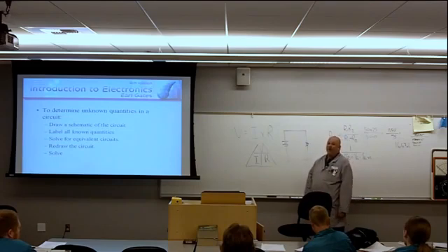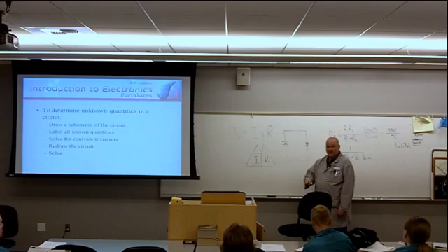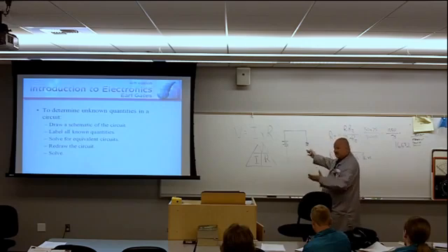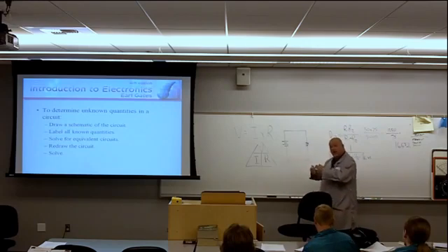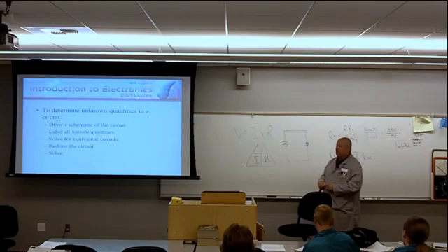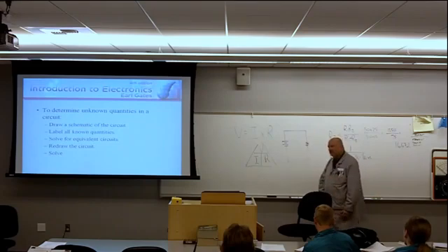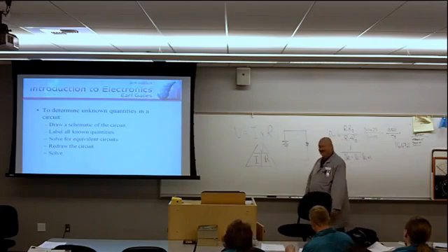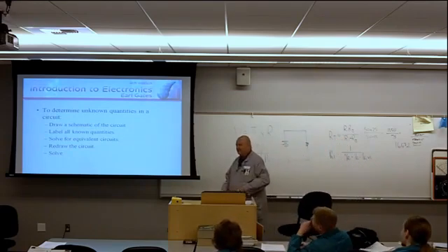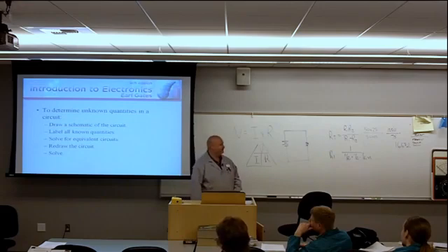And I'll tell you what, if you go out to your car and you turn the key and there's nothing, and you open the door and the dome light doesn't come on, nothing works in the car, all of a sudden this is exactly what you've got, and there's an open in this circuit, and it's a pretty big open, or your battery's dead. I don't think your whole load is dead. It's not like, oh my goodness, I've got to replace the load but save the battery. It doesn't work like that. But do you see the power of troubleshooting like that?